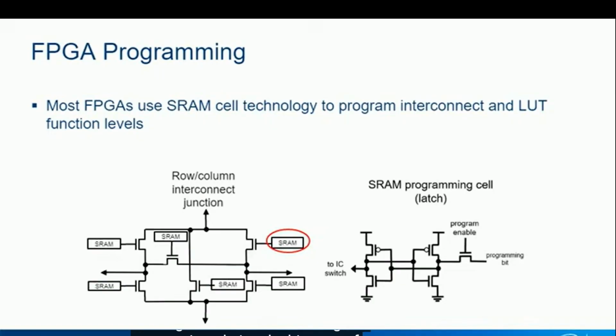Obviously, this type of programming architecture requires more transistors than a CPLD programming array. However, all the transistors are standard. No floating gate transistors are required, so no special fabrication is required. The main problem with this programmable architecture is not the number of transistors required, but the fact that it is volatile. Whenever powered off, the latch is cleared. This means that FPGA devices must always be programmed at power on to configure the device SRAM cells.